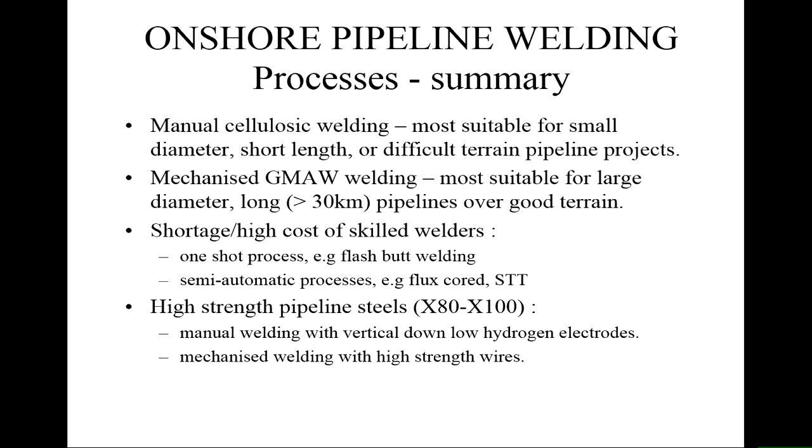Steel specifications in China and in the UK are different because the main sources of iron ore have different levels of contamination. Chinese steels have a lot of boron in, which is almost absent from UK and European steels, which have a lot of phosphorus in. So they are just different. You need different procedures. And you need to recognise that if you're then going to be in a multinational company, you can't just pick and choose process from one country and apply it in another one. It doesn't necessarily work.